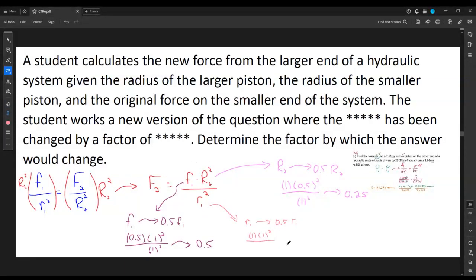It's a good habit to make sure that you're tracking that carefully. All right, and then here, 0.5 squared. So what we want to notice from this is that we end up with not quite just the reciprocal of the factor, but you need to remember that because of the area definition and the r squared that pulled across, it's the reciprocal of the square of the factor. So for me, that's the reciprocal of 0.25. This one's actually going to become 4. So it makes a rather large difference on that one.